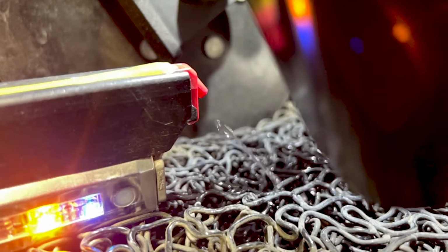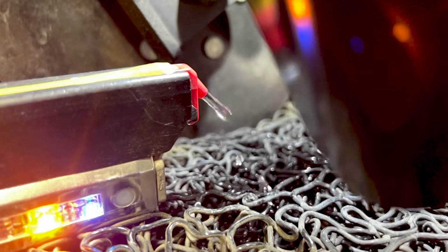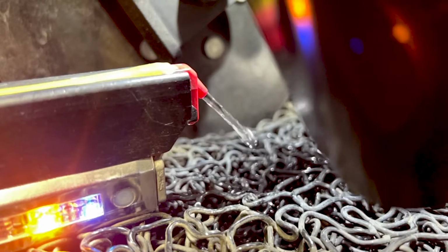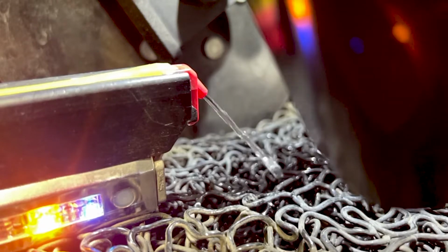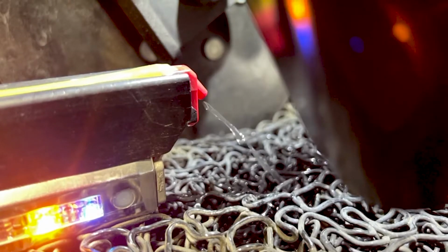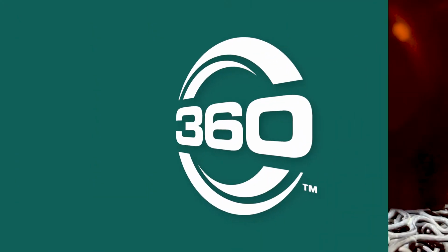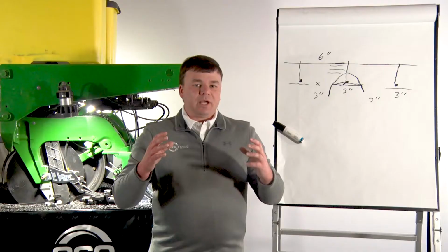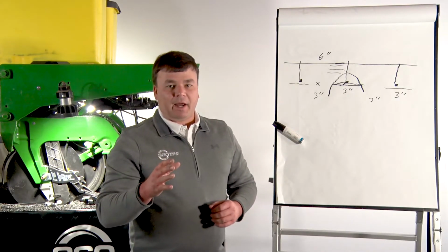And then as we travel 2 or 3 inches, however you have your timing set across the ground, the valve then slams shut, cutting off the flow. And so we're producing those, what we call dashes, on the top of each seed as we work our way across the field. So now with the dash system in mind, let's go back to the math